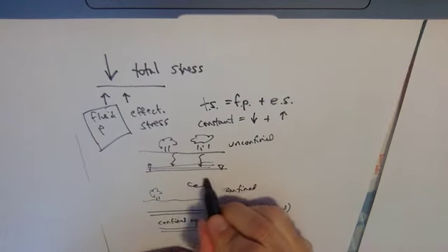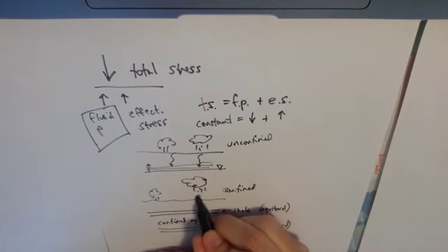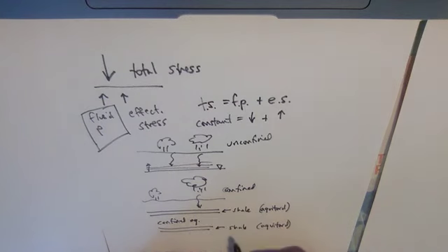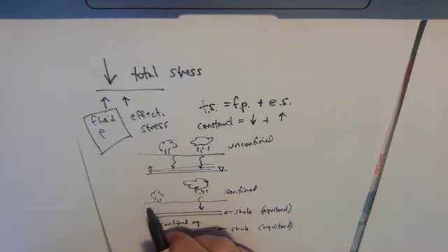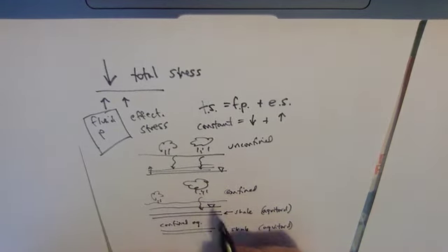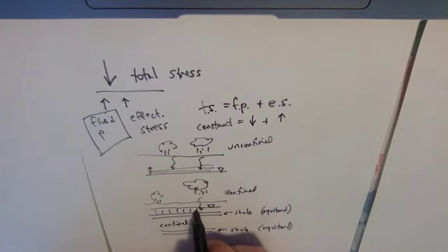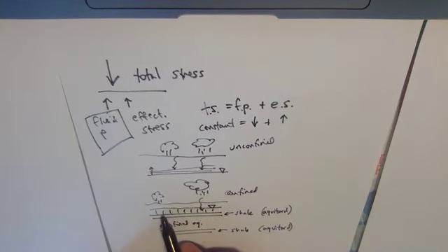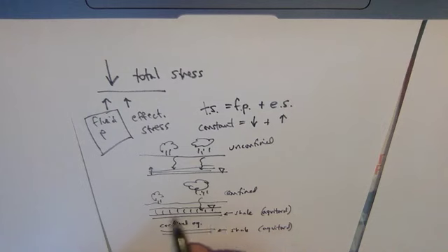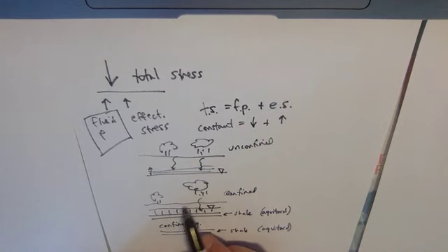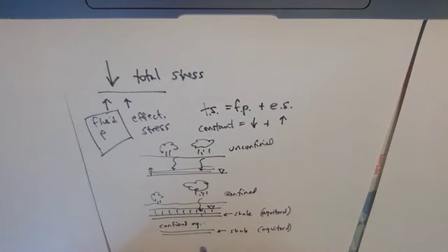So when it rains, the water soaks in, but the water will form an unconfined aquifer here that just represents this portion. Basically, the bottom of the unconfined aquifer is the shale layer. So you have an unconfined aquifer here, and the water has a very, very difficult time soaking through this shale and impacting the confined aquifer.